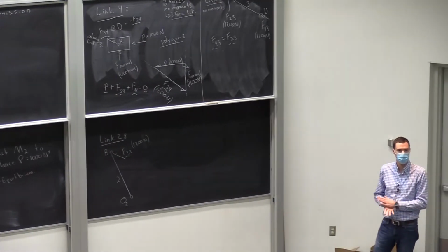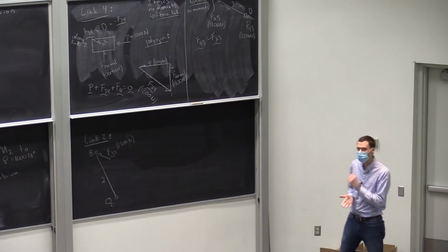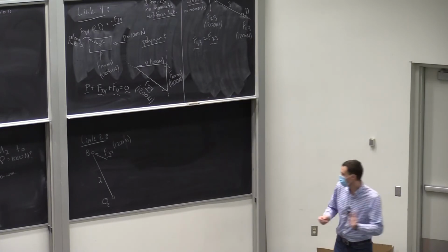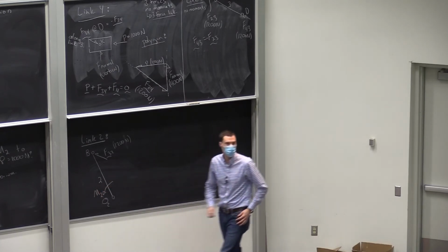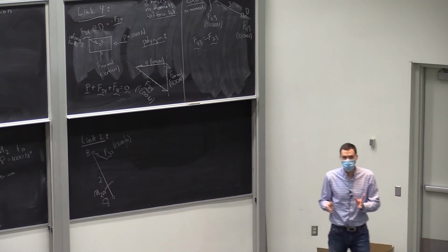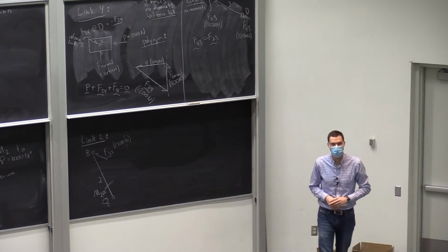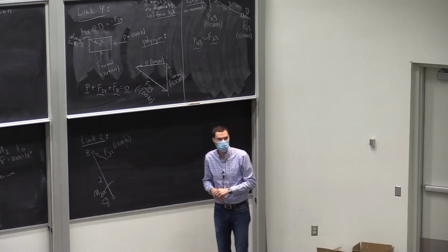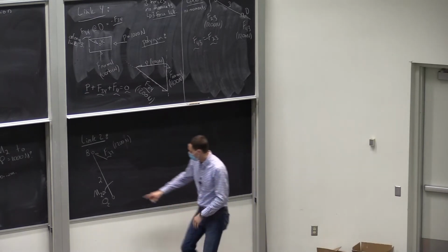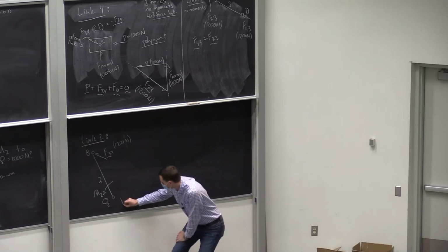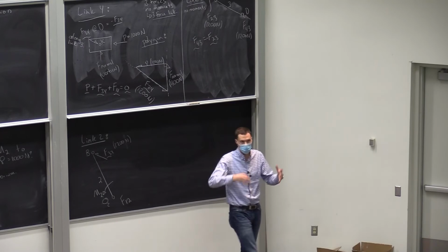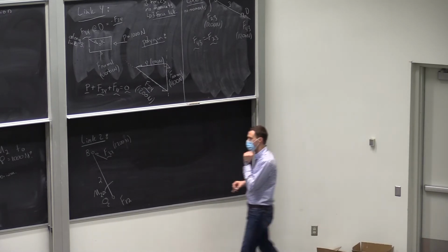Are there other forces on this link? Or is this it? Moment 2, yeah, moment's on there. Okay, is that everything? This is a free body diagram of link 2. I see you pointing up, yeah. The ground. Is that what you said? Yes, the ground. So this ground point is a turning pair as well, and that might also have a force, right? So anytime a link's connected to another something, there's likely a force there. It could happen to be 0.